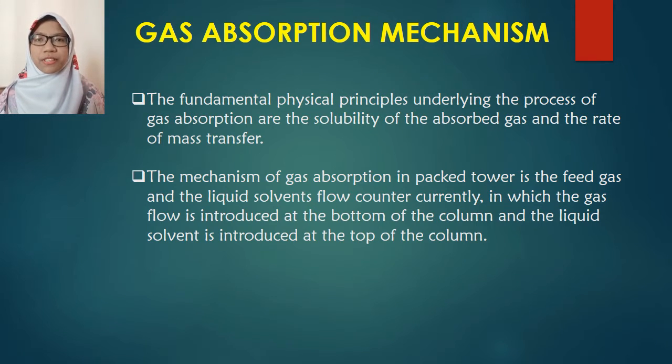I would like to explain about the gas absorption mechanism and the packing. The fundamental physical principles underlying the process of gas absorption are the solubility of the absorbed gas, which we also call the solute, and the rate of mass transfer. Packed tower is the most commonly used equipment in the gas absorption process.